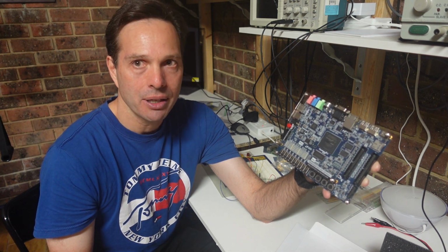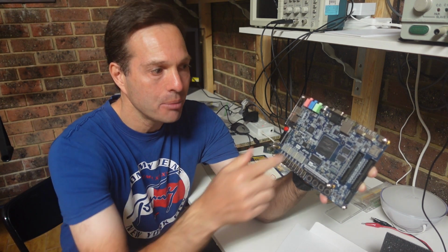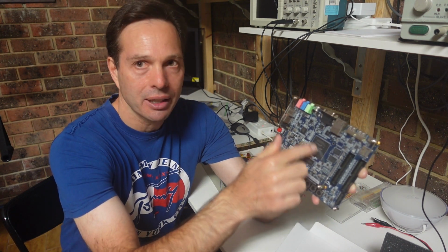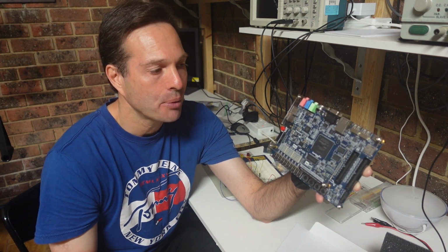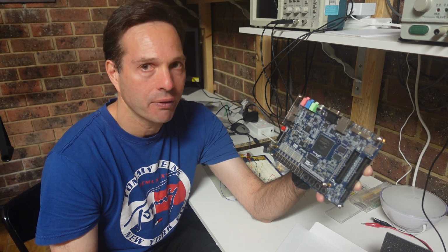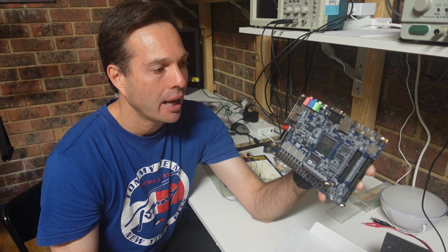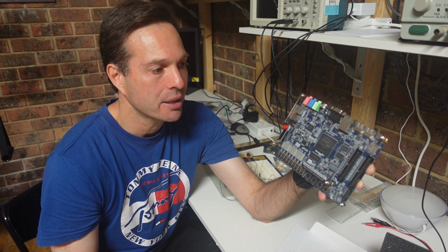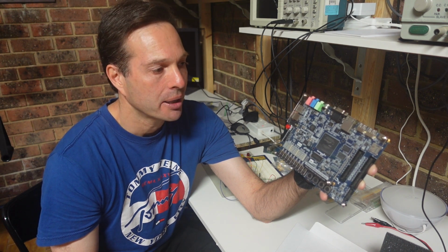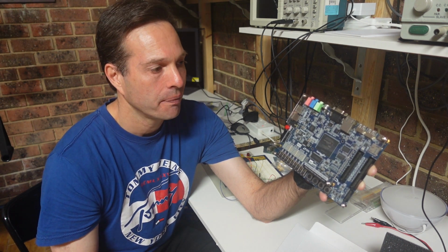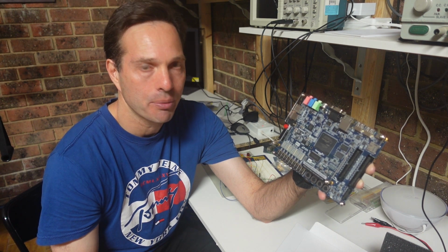Hardware description languages describe hardware. They allow us to describe the connections between the different logic gates and flip-flops inside the FPGA. The hardware description language that we will be using is Verilog. The other very popular one is VHDL, and if you are going to become a serious FPGA developer, then you'll probably need to know both, but it doesn't matter which one you learn first. I've chosen Verilog because I find VHDL very verbose.